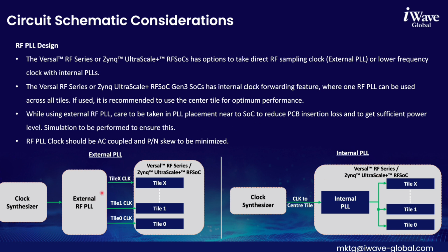When we select external PLLs, we can use TI's LMX or Analog Devices' ADF series PLLs. Another important feature that RFSoC Gen 3 devices and Versal RF have is the clock forwarding feature. As I mentioned, the RF channels are structured as tiles and we have to give the clock to all the tiles, so when we use external PLLs, we have to use multiple PLLs.